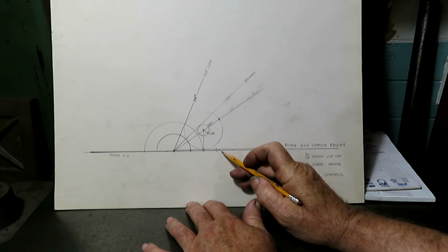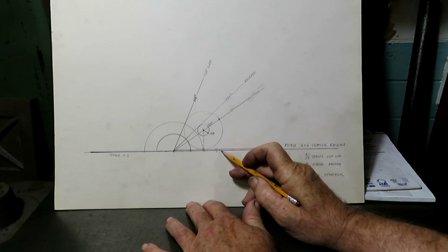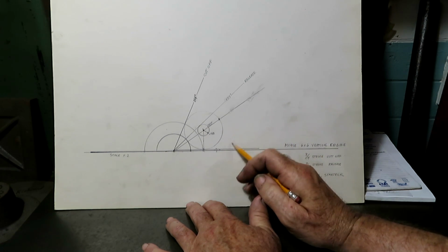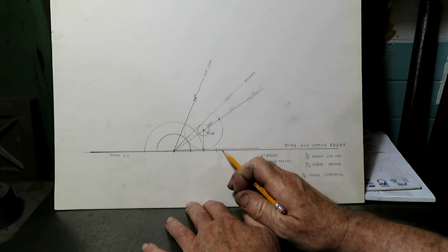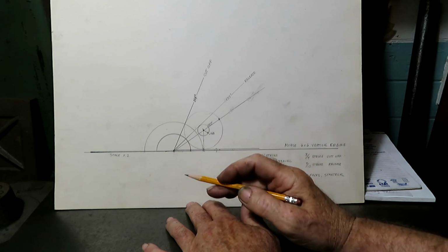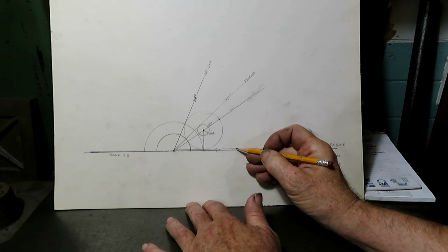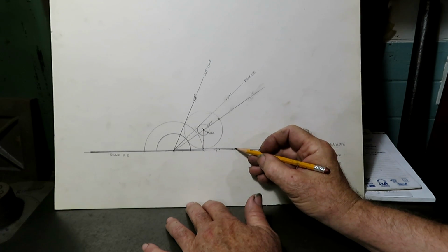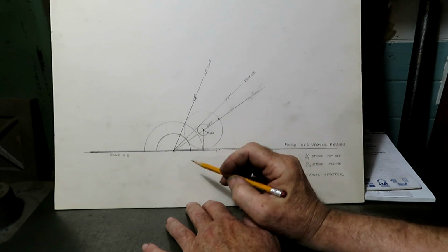It's a little like ignition on an automobile engine. You want a little advance on it, so you get the spark advance to get the fire going before the piston rolls over top dead center. Well, it's the same thing with a steam engine. You want to get the steam moving through the ports before it rolls over top dead center. And in the case of our Morris engine, I decided it should be a 1/16 of an inch. So this is ×2, so that's an 1/8 of an inch between there and there.